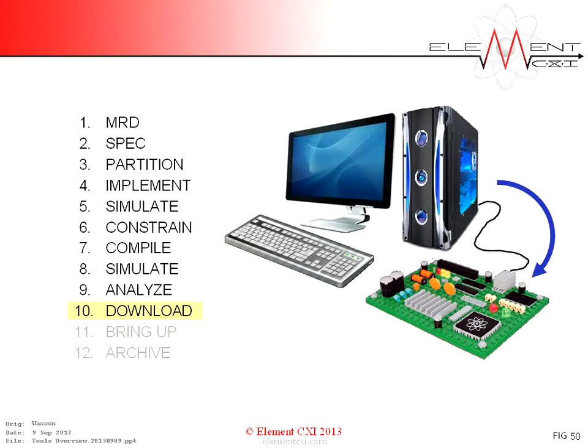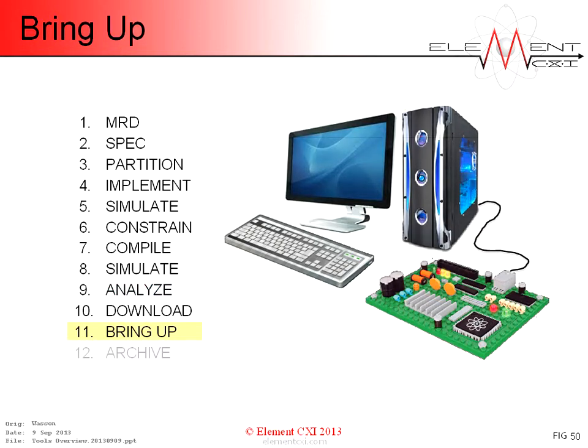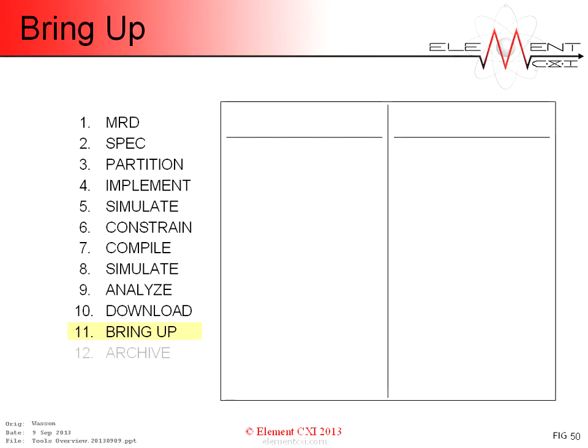After download, the design must be brought up, proven to work under real-world conditions. This step is critical for cases impractical to simulate or for detecting and resolving problems not exposed by analysis. The long list of problem cases falls into two general categories: physical and logical. While physical problems aren't design problems, they are obstacles to bring up. These include having a bad device, board, or test bench.